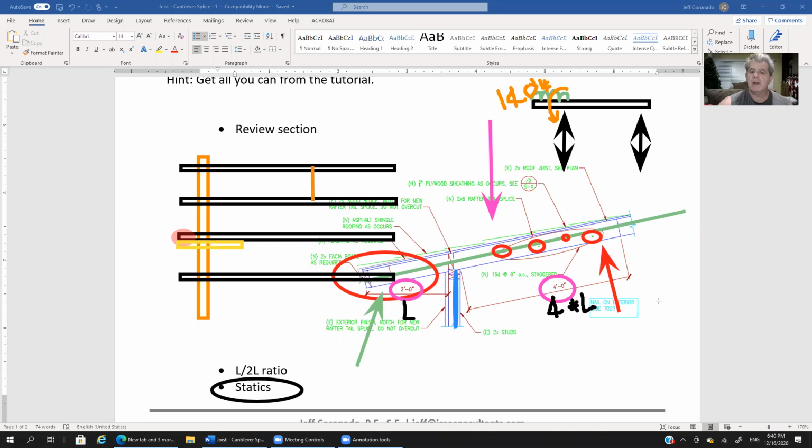So I've got 140 foot-pounds, and I'm going to divide that by the distance between my supports, which gives me my reaction at the back end. So that's 140 divided by... we don't exactly know this distance. We know that the total distance is 4 feet. However, this last nail isn't at 4 feet. What if I conservatively say this is 3 feet? So I've got 140 divided by 3. That gives me, let's say, 40 max. So I've got 40 pounds on that outlier nail.